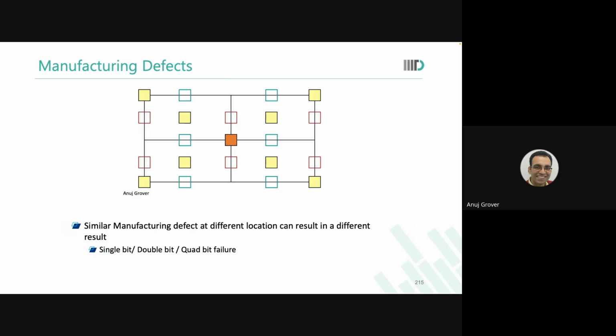And you will notice that when you manufacture or when you start to test SRAMs or structures like this, you will see that many failures are single bit failures, which could be because something internal to the memory cell failed, or which could be because of SNM failing or writability failing or anything. Now you can't tell much about it.